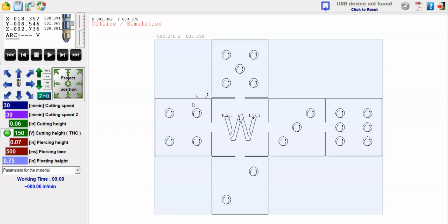However, if you do decide to go that fast, there is a hotkey for that, and that's to hold down the shift key. So if you hold down the shift key on your keyboard and hit your up or your down or your left or your right, and if I hold down my shift and hit right, it's going to increase and travel extremely fast. Same thing, shift key, and you'll notice my X values here are moving incredibly, that's my plasma on, incredibly fast through these numbers here. So just simulating that, moving rather fast.